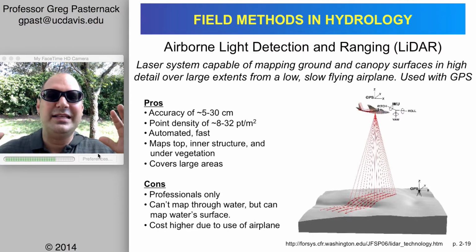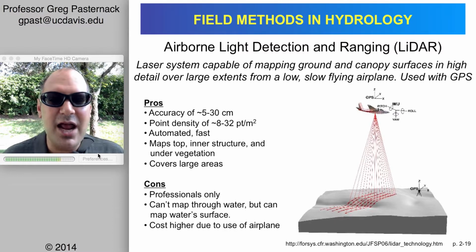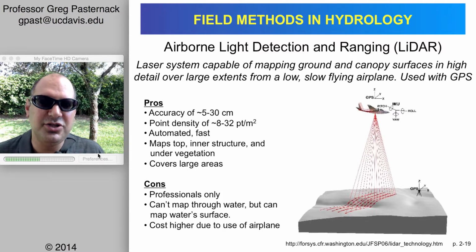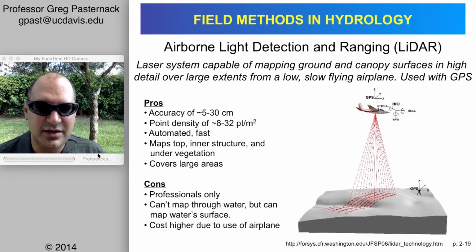And if the water is crystal clear, and doesn't have air bubbles and a lot of junk in it, turbidity and debris, then it can pass through and hit the bed and come back. So if you pair a red LiDAR package with a green LiDAR package, you can map everything. Green LiDAR is still an emerging technology. It has a lot of limitations, but it's emerging relatively fast.